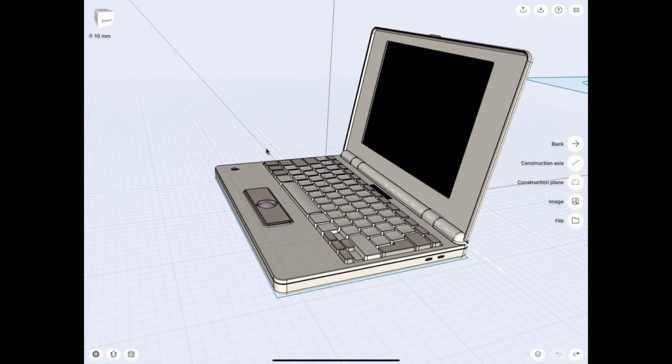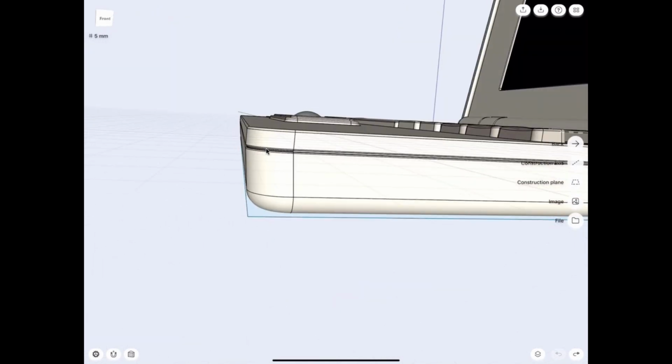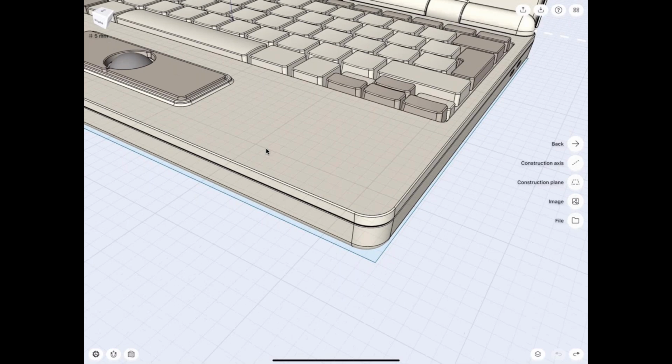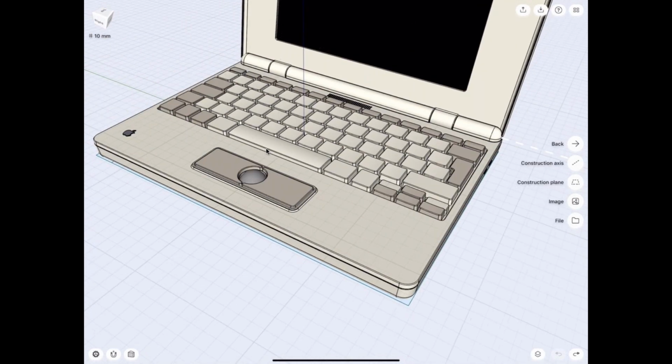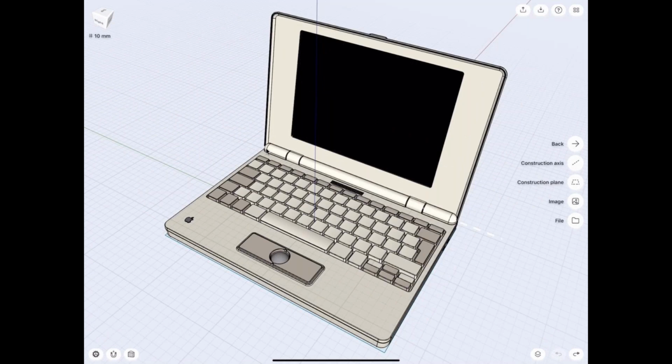I mean, that goes without saying for things that you want to manufacture, but also concept designs as well. You're sort of given more free rein in concept designs, but the earlier you can put in the draft angles, the better. Believe me, in the past, we've designed things for Precipice Design, and it looks amazing, and it can fit the electronics inside really well, and it's the smallest thing and the thinnest thing that we can possibly do. But then as soon as you realize, oh, we have to add draft angles and tolerances and wall thicknesses, then it starts to change the design. So without getting yourself caught up with that later on, planning for that earlier on is really going to help.